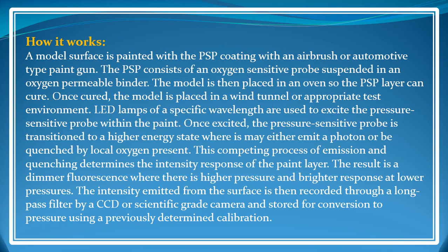So we are talking about probes, okay? And what type of probes? We are using an oxygen permeable binder that contains oxygen molecules, and those probes emit or illuminate after we get a source light with a fixed wavelength. We can read the output by photodiodes or photo sensing devices. So in this example, output voltage will be generated, and when pressure is applied, the output illumination quantity will change. And how it changes we are going to talk about.